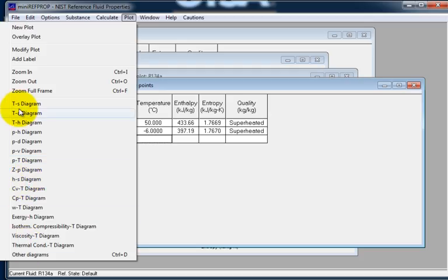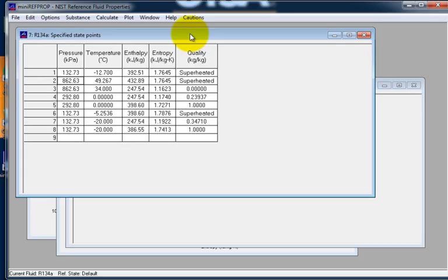The ones that I like to look at are pressure entropy and pressure enthalpy, or temperature entropy, TS, and pressure enthalpy. Well, what I did for this problem is I worked it up. It took me a little bit, so I got the same numbers in the line for the states that are there, which wasn't easy to do. But if you want, you can compare these numbers with the other numbers. They're not exactly the same. They're off, but they're close. And they'll give you the same final answer, mass flow rate and mass fractions as well as that.